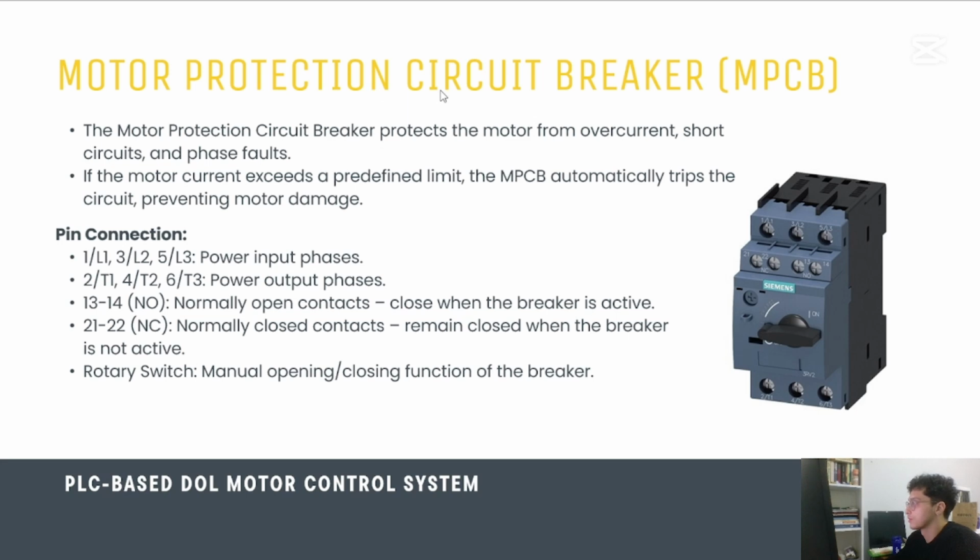Motor protection circuit breaker. The motor protection circuit breaker protects the motor from overcurrent, short circuits, and phase faults. If the motor current exceeds a predefined limit, the component automatically trips the circuit, preventing motor damage.